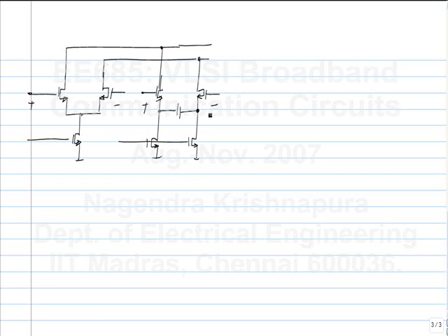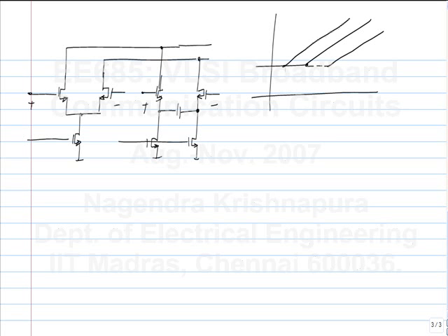How would you control the coefficient in this case? So there is only 1 degree of freedom. The coefficient that I am talking about is, so let's say you have a boost here. If you lower the equalization coefficient, the response becomes something like this, or if you increase it, it does this. So it gives you more or less high frequency boost.